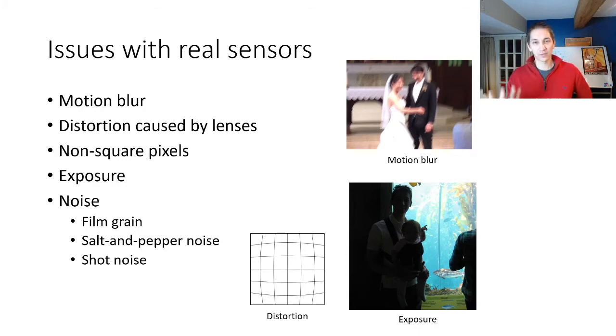And so we'll oftentimes toss out images that have poor exposure or motion blur, etc. But we can't control this so well on our robots. And so here we have to worry about these types of things and develop algorithms somewhat specifically for robots if we're going to make them reliable, especially for example, moving robots or robots that need to work with very different lighting conditions.